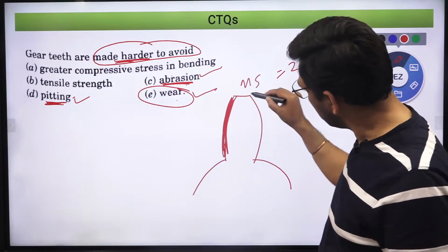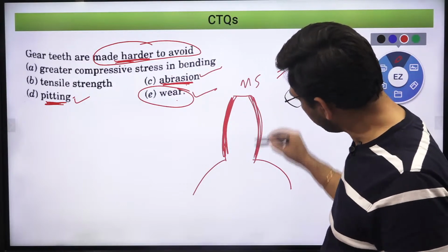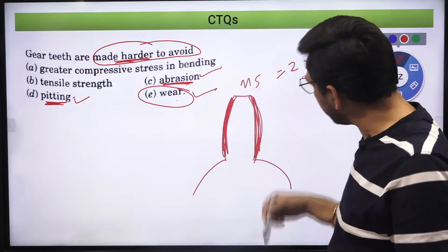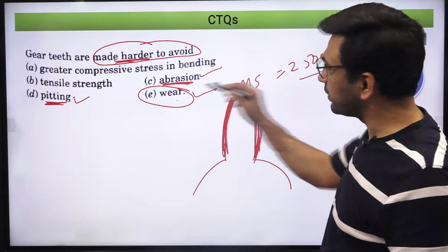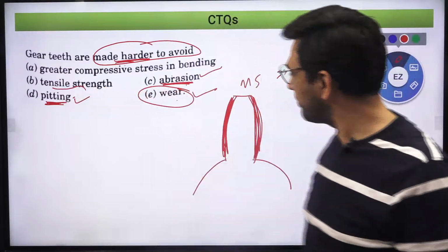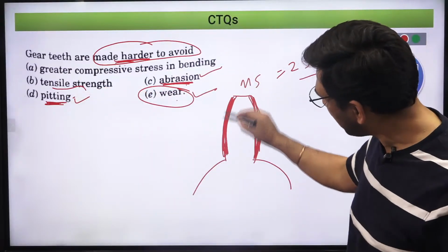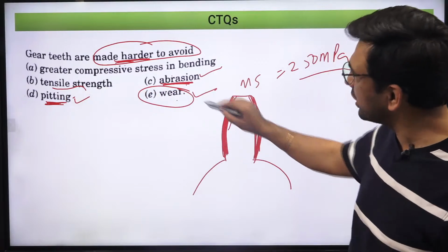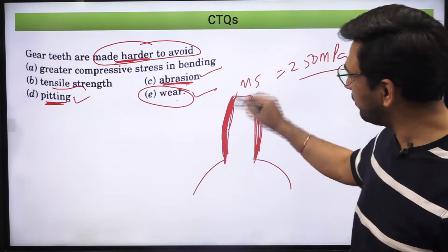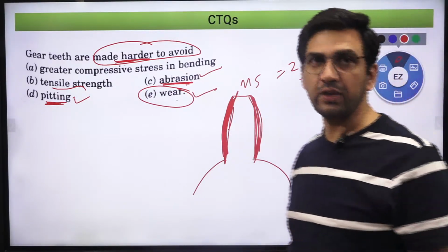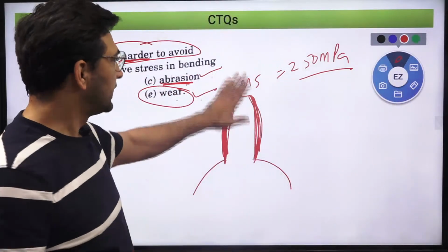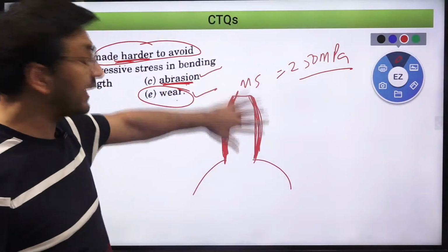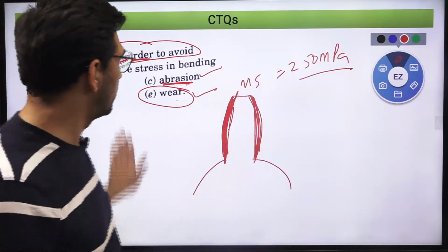So do you think that this hardness will get increased? In totality, the tensile strength of this particular gear tooth will remain the same, but only the surface layer which I am hardening, its wear resistance, all that will increase, like with carburizing, nitriding, those surface hardening processes which you can make use of over here.